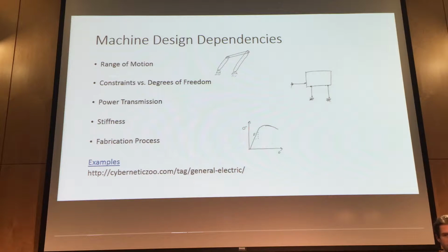I have this ThinkPad, and all across the bottom here, there's this bulge. That's because they tried to shove a bunch of stuff in there, and they weren't really keeping track of the tolerance stack of everything that needed to fit inside. They didn't care, they weren't driving that. But if you manage all those constraints, then you can actually get really nice hardware. And that's what we're going to talk about a little bit.